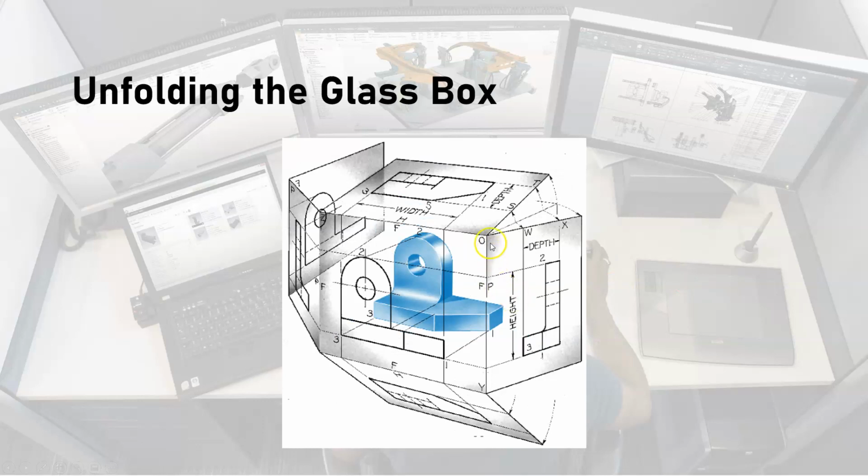And as we unfold the glass box, we have these hinges right here and right here. And as we bring the top view projection plane up and rotate it up, this alignment occurs naturally. So this edge right here is naturally aligned with the edge in the top view. Same right here. This edge is aligned right there. Same with the right side view. So this bottom edge is aligned. It comes around the hinge and it goes down here. And the top surface, likewise, is aligned. It comes to the hinge and then banks around there.